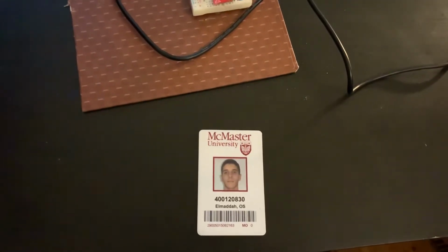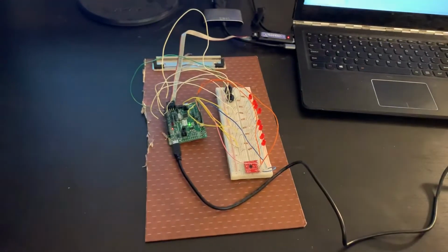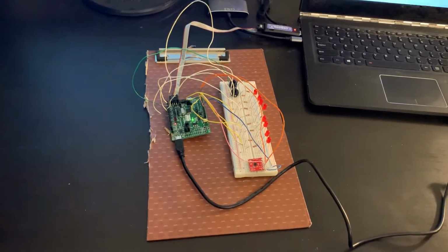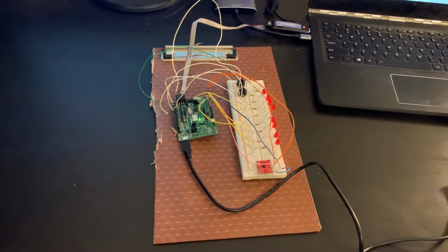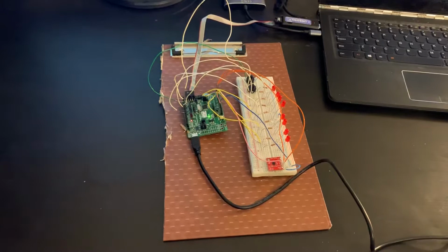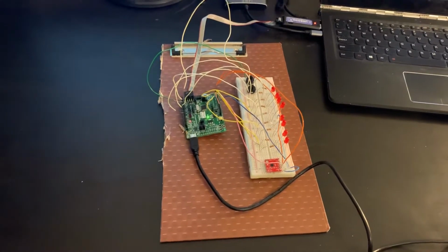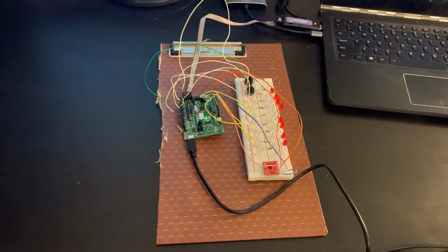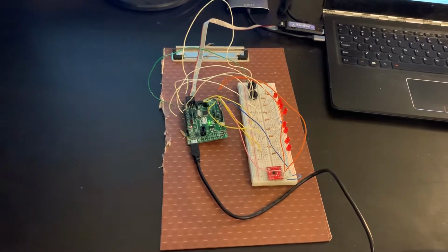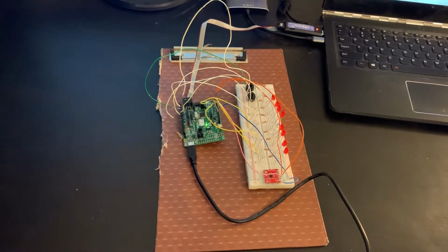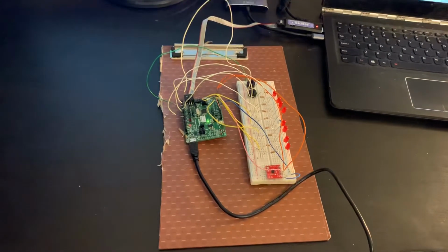Based on my student number specifications and being assigned 8 megahertz as my E-clock frequency, I had to calculate the baud rate, the new baud rate divisors, and the error based on the 8 megahertz. Based on my calculations, I found out that the error for most of the baud rates was 0.16%. But after 38400 as the baud rate, the error becomes more than 10 times bigger. We were supposed to select the highest baud rate possible. So that's why I used 38400 as my baud rate.